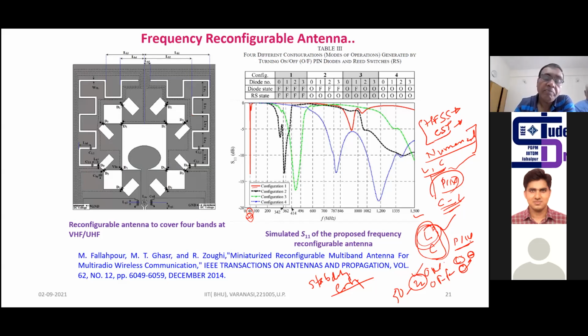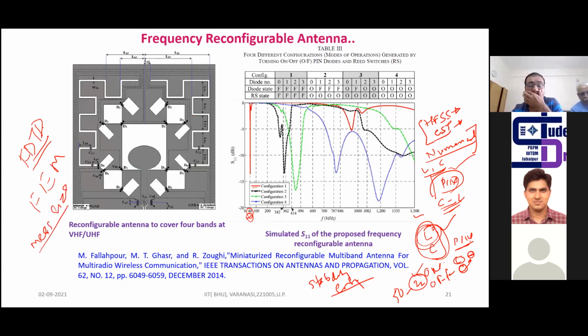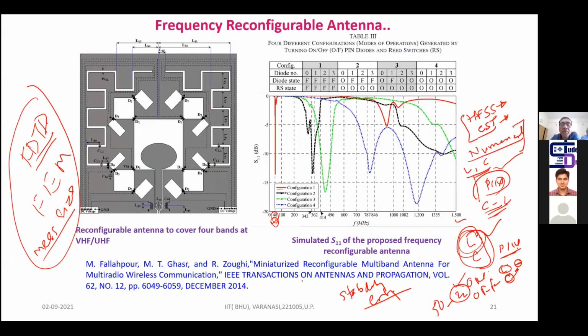If you read about FEM, it has some criteria; FDTD has some, okay. And that can be defined with the help of mesh size. Now, in simulation software, how can you check? Theoretically we know this. First, you have to see whether your solution is stable or not. If your solution is not stable, like what you saw right now, you get some notches, some flickering effects, some spurious effects from these lines, right?